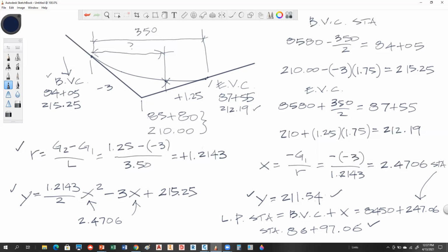Yep. Okay. Why are those critical points on this highway? What's happening there? Well, that's where the parabola would level out. Okay, so what's happening there besides that? I agree with you 100%. What's happening when it rains, Jake? It's level, so the water stays. Yeah, so you got water coming down this way on you. You got water coming down this way on you, and guess where it's going to pool? Right there.